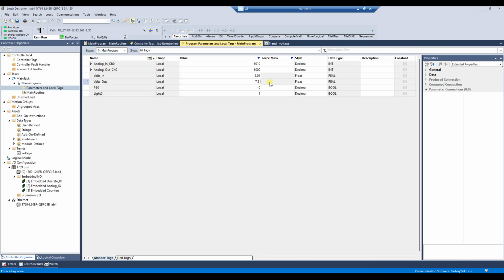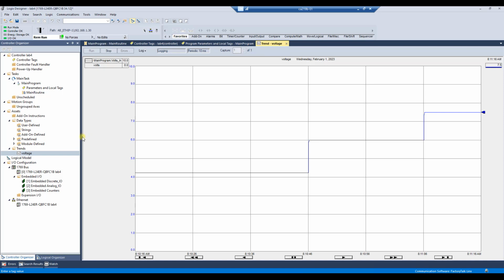In the lab, you will be doing this by changing the knob on a voltmeter. Now make sure you don't exceed 10 volts. That again can damage the PLC. So I go back to my trend chart, you can see I'm at 7.5 volts. Now, when you're using the power supply, you'll get much smoother curves as this changes. Hopefully, these few demos will help you out with lab number 4. Part A is working with analog I/O, and the second part will be working with temperature.